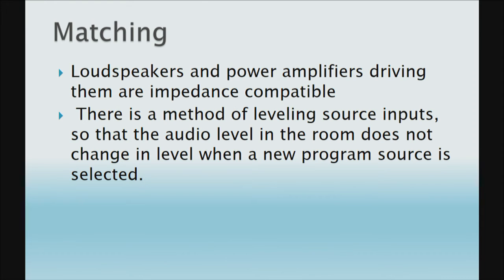And then we get into, when we're looking at AV designs, matching. I'm getting into some granular details, stuff I've seen and other folks have seen over the years. Making sure your loudspeakers and your power amplifiers match. I recently was on a site where they had some nice JBLs up there and we just couldn't get any level out of them. Went out there, it was the model that, guess what? It's got a 70-volt switch on the back and they're all set to 70 volts. Minor detail, but it sure impacts your system.